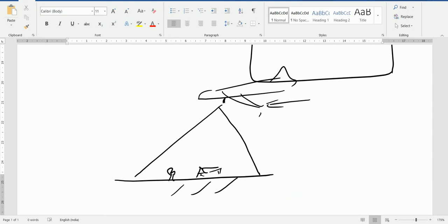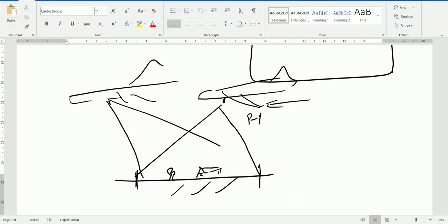After passing this area, for example, it has taken one photo, and after crossing the surface, this is the new position of the plane, and again the camera will turn back and take a photo of the same area. In this way, we have two photographs from the same place, and this is what we call a stereo pair.